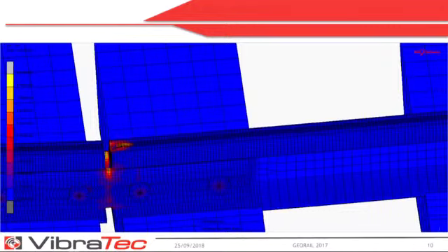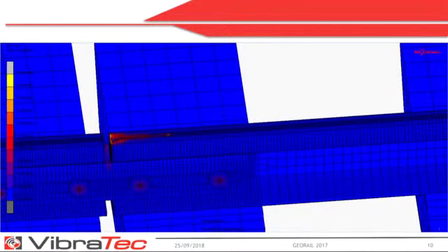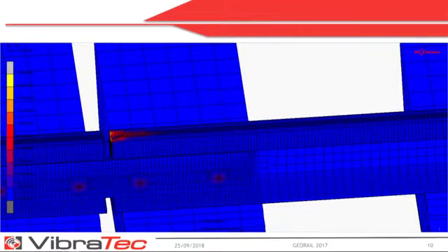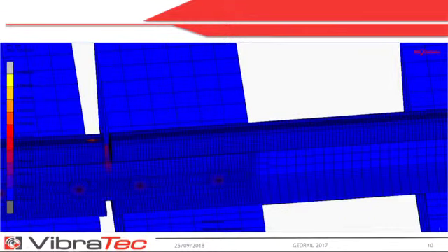So when it goes onto the rail joint, then it goes further, and you can see the residual stress here. And here it's the loss of contact, and it will come back somewhere here. So then you have the P2 peak here after the resonance.